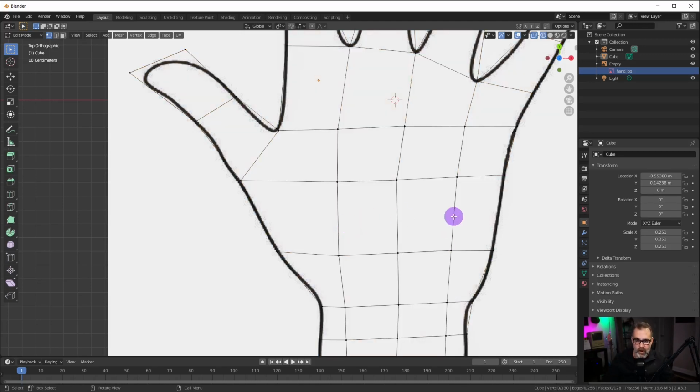Okay. You always want to ensure that your geometry is nice and smooth, and we always want to have a box. Okay, we want to avoid triangles because when you're going to apply certain modifiers, such as the subdivision surface modifier, which we're going to do in a few moments, it's important to always make sure that we have basically four edges all the time. Basically squares. We always want to ensure that we're modeling with squares, not with triangles.